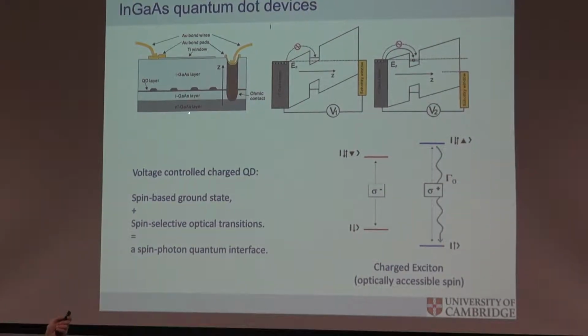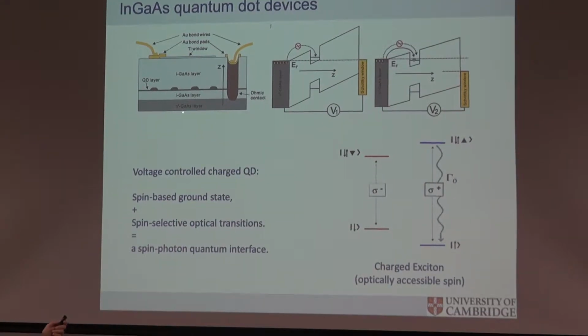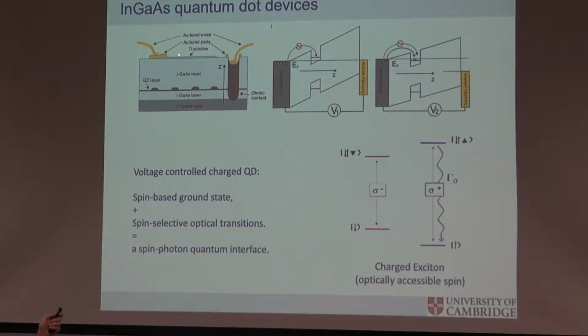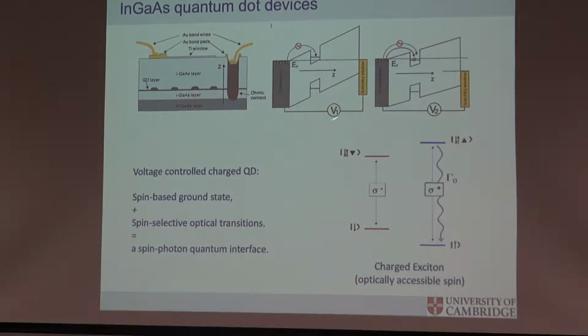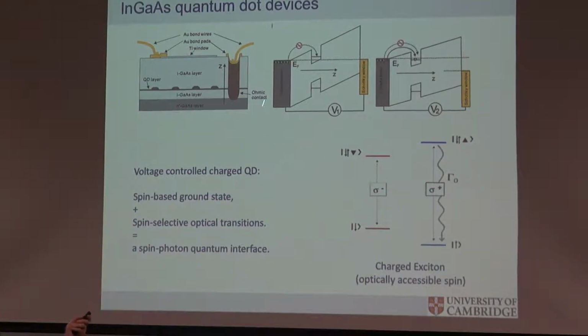And then we put them in electrical contact, so we make devices out of them, so we can control some of its properties. We have an n-doped layer, an electron gas, if you will, with a tunnel barrier, and then a Schottky window to be able to apply a voltage in the lab. What this provides is a comfortable region of around 200 millivolts, 300 millivolts, you can easily apply in the lab, of charging plateaus. So we can load up, we can keep the charging state of the quantum dot as empty, like you can see here.